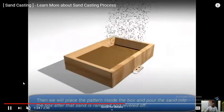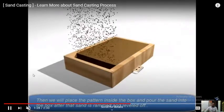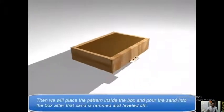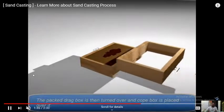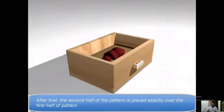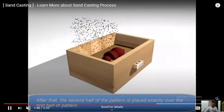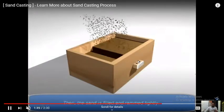properly, and it will be filled up to top. It is just inverted molding drag box, so we will just make it upside down, and you will see this just making it upside down. And then we will put the cope box on this, and dowel pins will be used to just fix it so that it doesn't mismatch. And after that the other half part of the pattern will be put and molding sand will be rammed on it. You will just see here dowel pins have been put, and then this ramming will be done.